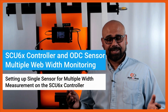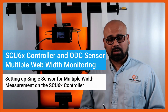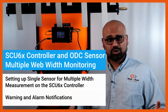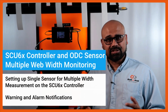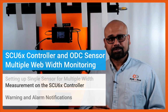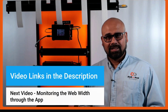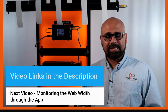Just to summarize, in this video we looked at how to set up a single sensor for multiple slit width measurement, which you can set up directly on the SCU6X controller. We also saw how, when you connect to a digital stack light and the width of any of these lanes goes above or below the limit, you have the ability to trigger that stack light. In the next video, we'll look at how we can collect this data through Ethernet and what functionalities we have through Ethernet. We'll also look at the app and the data that we can collect from the app, and so on and so forth.